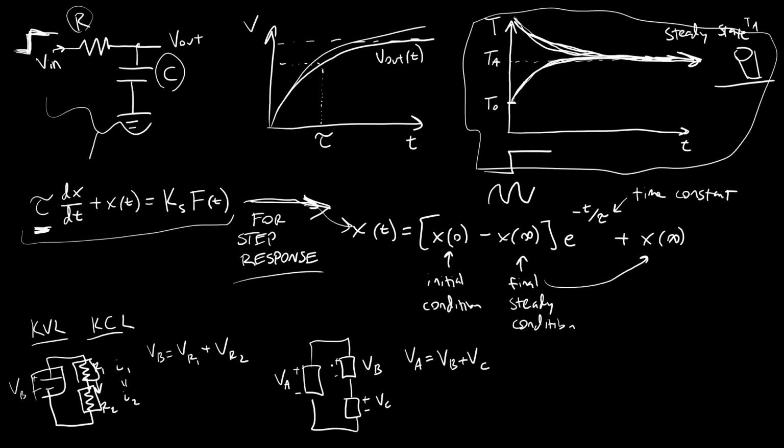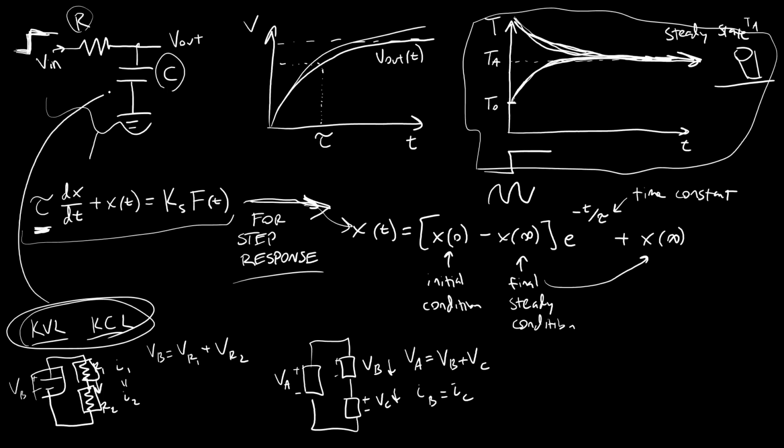Doesn't matter if these are resistors, capacitors, inductors, or batteries. This law still applies, and the same thing here. I've redone my subscripts a little bit, but IB equals IC, which is going to equal IA plus or minus, depending on how you're doing your sign convention. But these two things apply to resistors and capacitors, which is going to make them useful for analyzing this circuit.